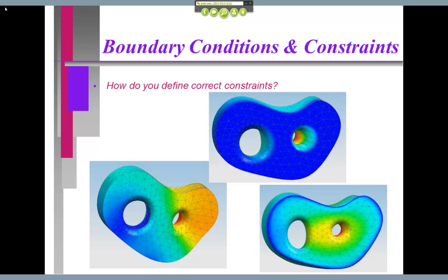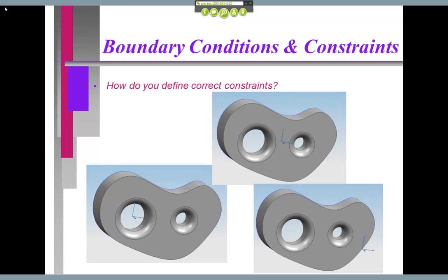So if we take just a minute and apply it to our car, let's assume that we're going to try and do the finite element modeling of the main frame or chassis. How are you going to constrain it? How would you hang on to this chassis to make it a realistic analysis? Okay, by the points where the wheels attach.